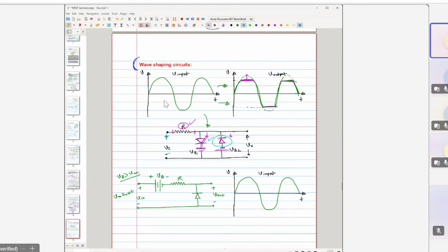But what about the other battery that we have connected? This battery has its positive terminal connected to the n side, and that makes this diode reverse biased. So a fight is going on between this Vi and this Vb, as to who can dominate. As long as Vi is lower than Vb, this diode cannot turn on, so it would be off.